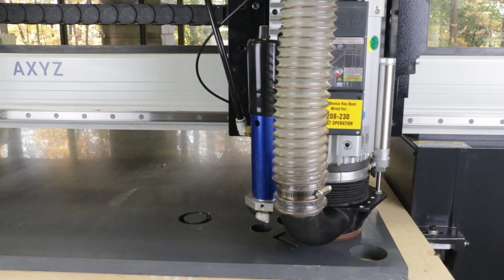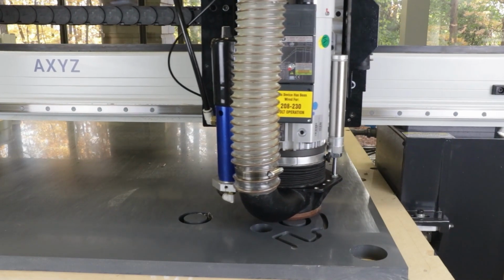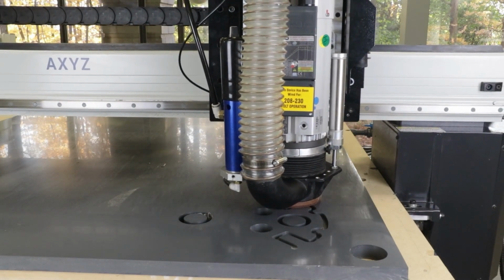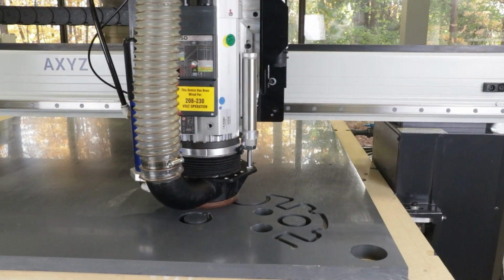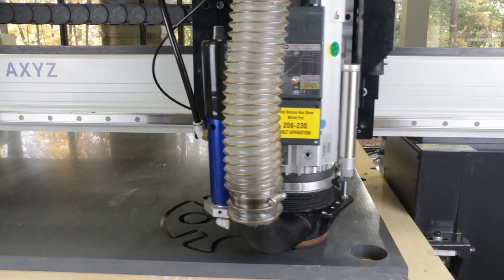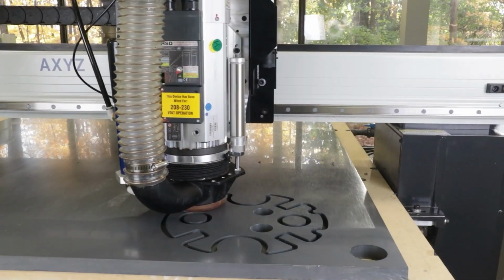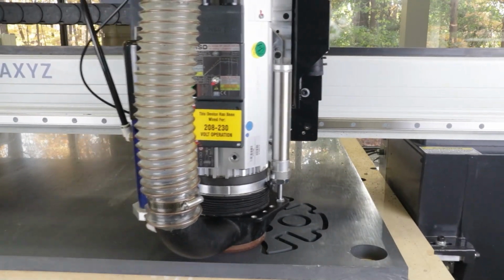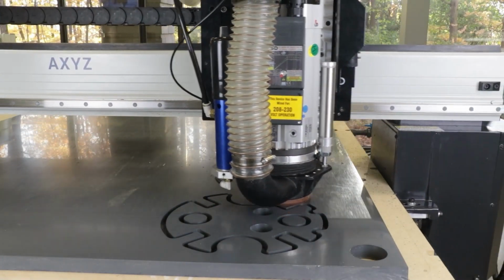Another thing you'll notice is on these 2 smaller size holes, we cut them in 2 separate ways. So for the very small holes, we went ahead and actually pocketed out the entire piece of material there. On the larger sized holes, we just did the perimeter cut, but because those pieces are still too small for the vacuum table to hold, we left on little tabs that can easily be broken off and cut near the end of the process.